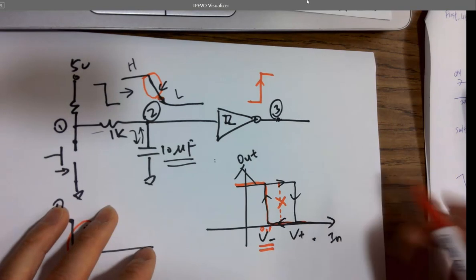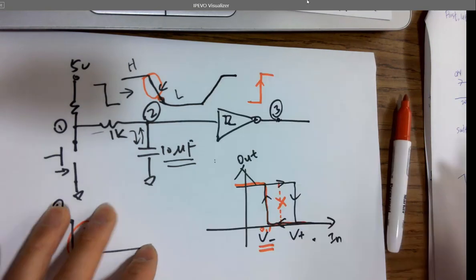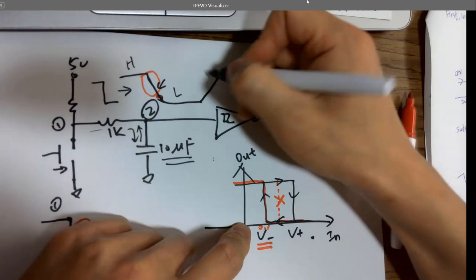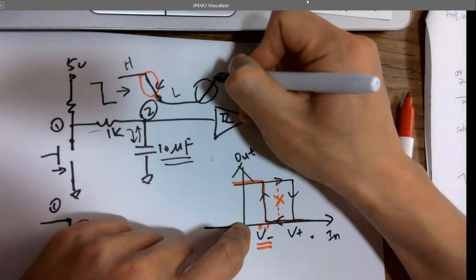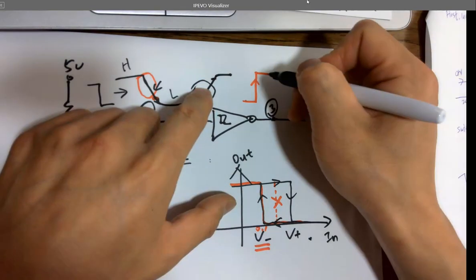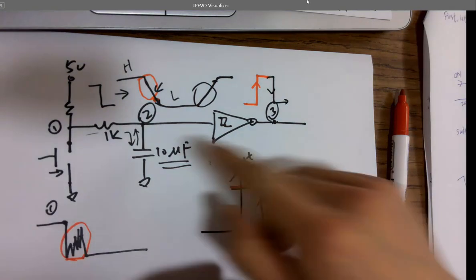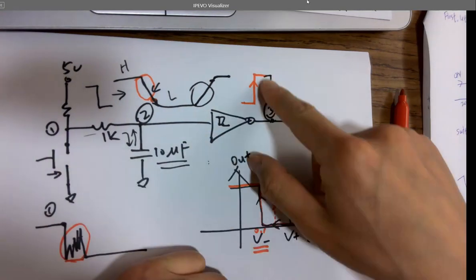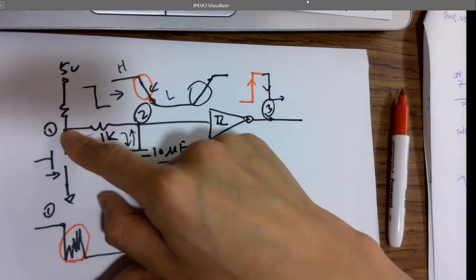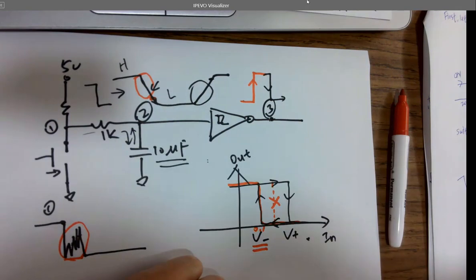That makes sense? So what about a very slow rising edge? Same thing. So this part is not going to do anything, but until this point, it reaches a positive threshold. It's going to give you a sharp falling edge, right? So you can nicely debounce the push button, but you get an inverse signal instead of exactly what you have over here, which is fine. It's just a switch. Does that make sense?